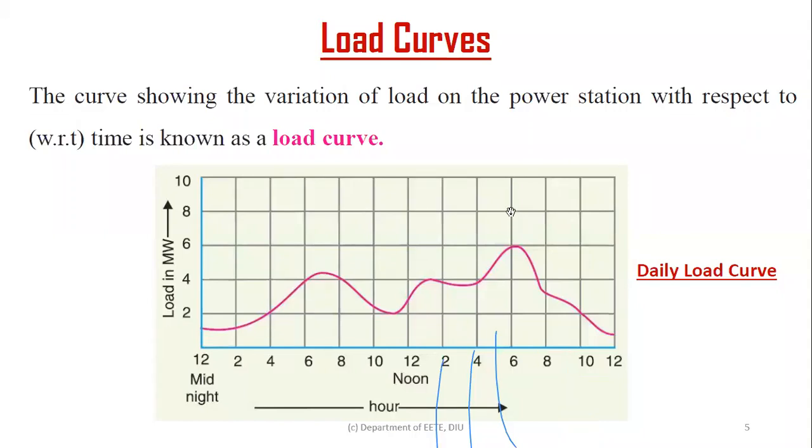So basically we are taking 8 minus 6, 2 megawatt, as a reserve capacity. At that time it can definitely give 6 megawatt, but for future expansion we already have 2 megawatt in reserve. So if more consumers are added in future, they can also be supplied from this power station. I think you are clear. I'm discussing this topic a little bit earlier.